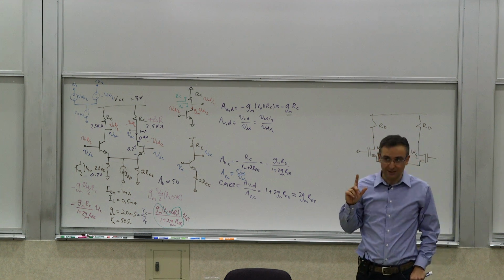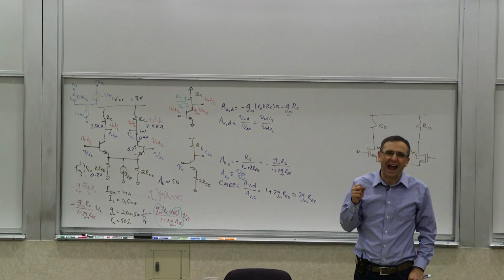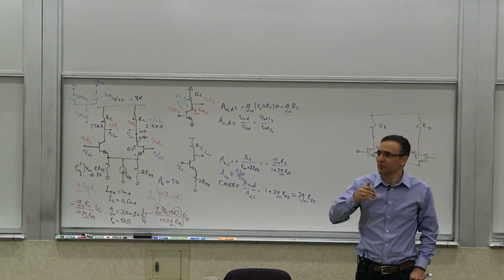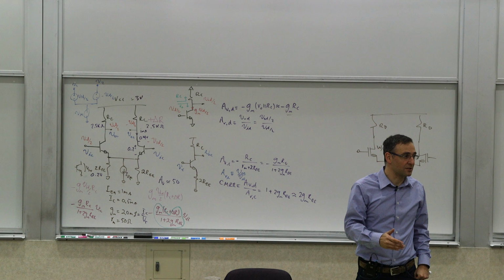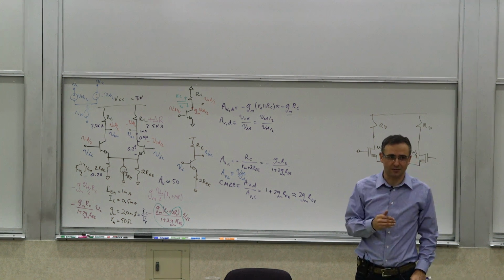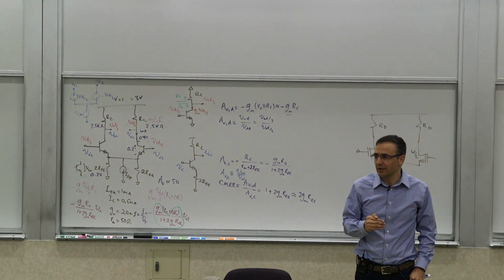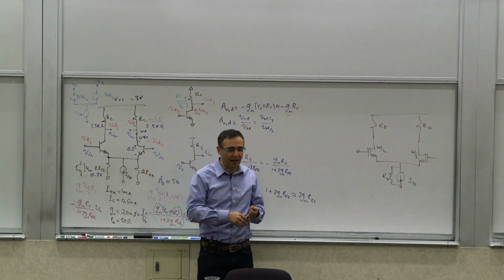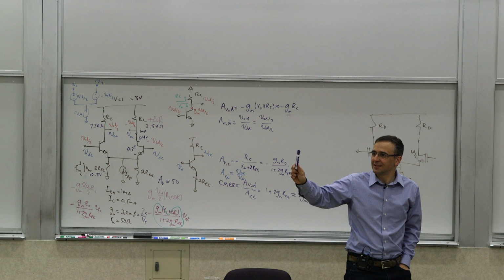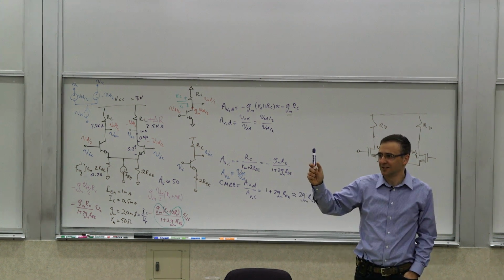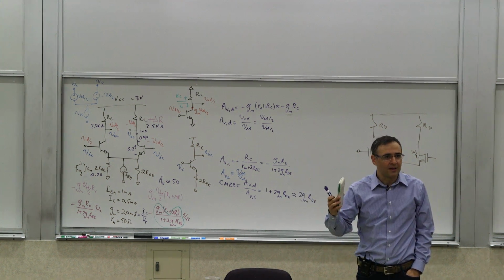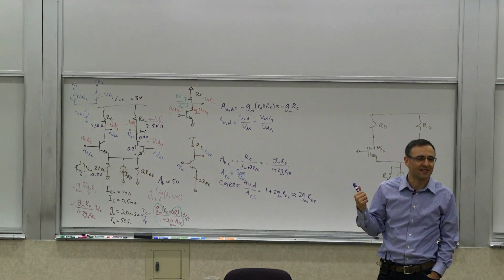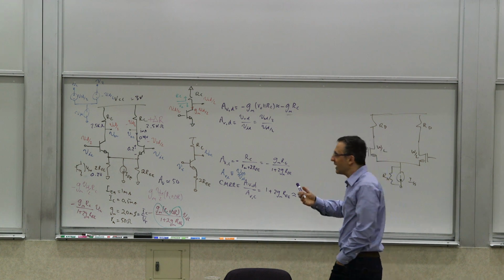But that's part of it. The other thing, more accurately, is the time constants, as we'll see. The time constants come from the product of capacitors and resistors, or the ratio of inductors and resistors. And we'll see that. But here's what's happening. The other thing that controls how fast I can move this is how strong I am, for a given weight. Now, what is that strength in electrical equivalence? It's the drive, right? It's the GM.